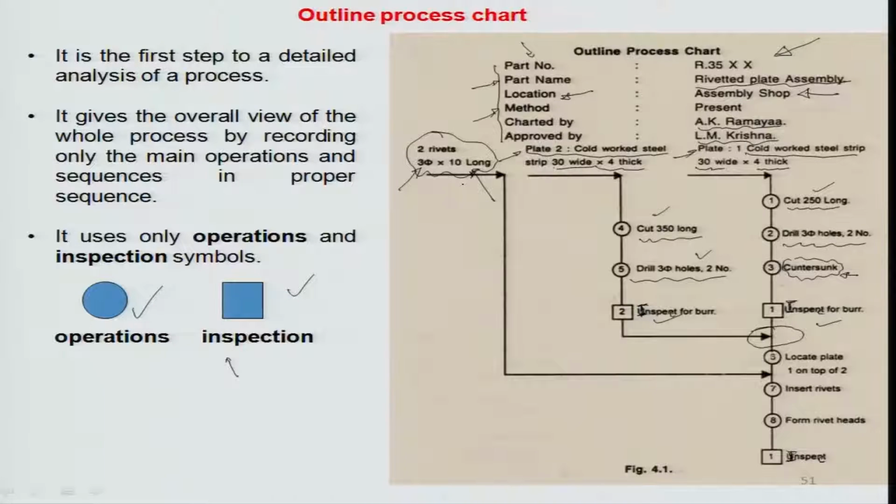These rivets are put together. So this rivet comes in here and is inserted into the overlaying holes on the top sheet and the bottom sheet, okay, because the rivets are coming all the way to this location and getting inserted here, and then we are forming the rivet head so that there is a lock on both sides, and then again an inspection happens.